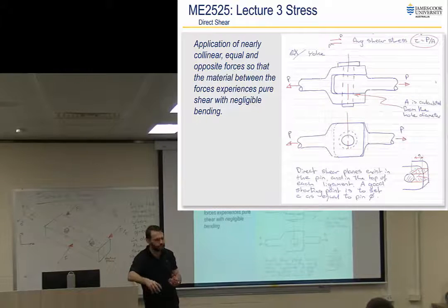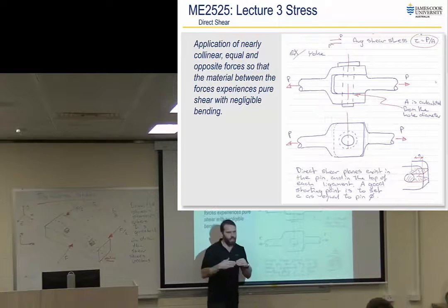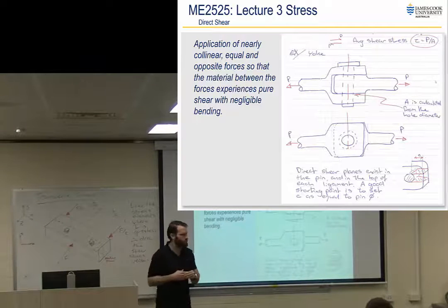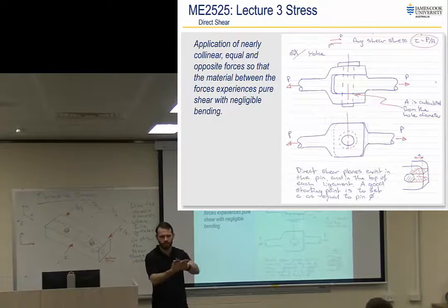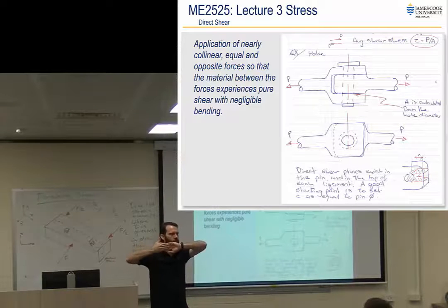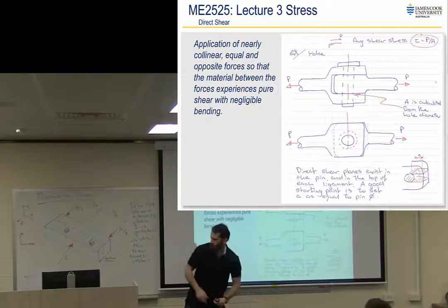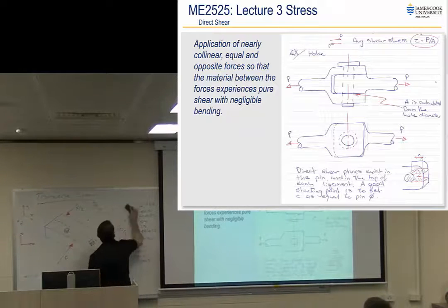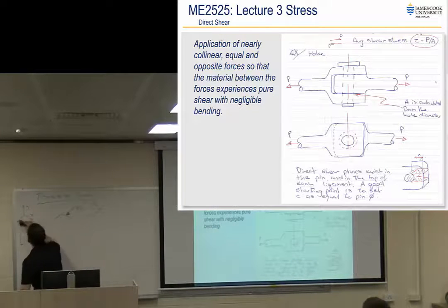The other thing is that it's not just that pin that will have that shear stress applied to it, because obviously the pin is imparting force back on the yoke, and so there's parts of the yoke that will have that stress, and the same goes for anything where you put a bolt through a hole and you actually put tensile load on that bolt, or shear load. You have single shear. You guys know what single shear on a bolt is? Bolt, pin, anything like that.